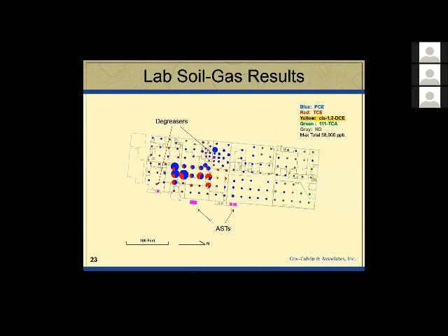We followed up with those small glass vials I showed early on and sent them to the lab. What we do now is we would normally send only the hot ones on the basis of the field PID. We'd send only a select number of samples to the lab instead of having to analyze all of them. But at that time, we were paying $100 a piece for the little glass vials. And we get the same kind of data, except we can see which compound is what. Blue is one compound, red is another.